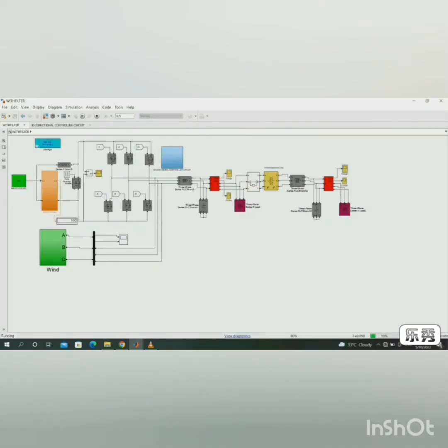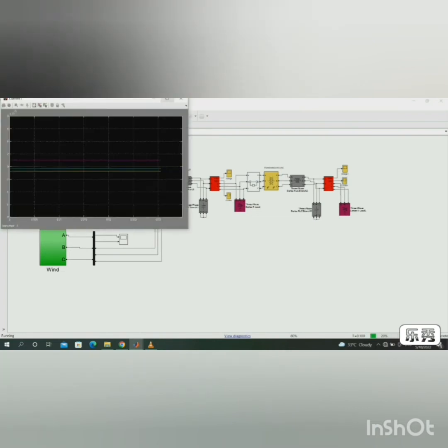From the RLC branch, we calculate the voltage and current. Both wind and solar are connected to the bidirectional DC to DC converter. Then in the three-phase transmission system, it is connected with two RLC branch circuits in which resistance and inductor values are given. It is then connected with voltage and current, which is in series with a three-phase RL load. The variation in harmonic loss is noted and compared with the without-filter harmonic loss values. Then the running process takes place.